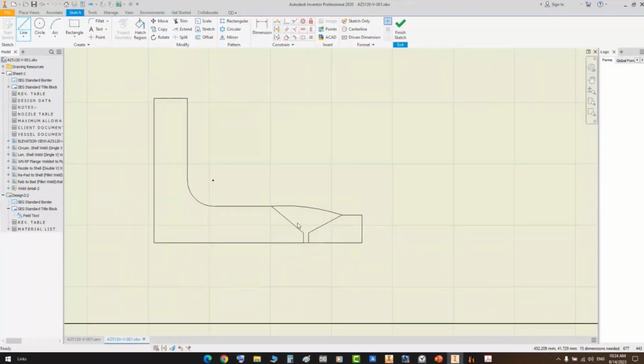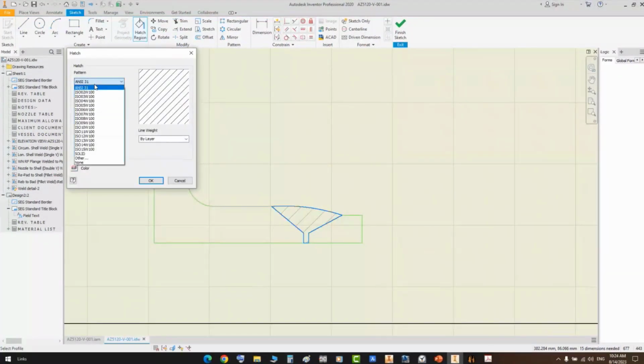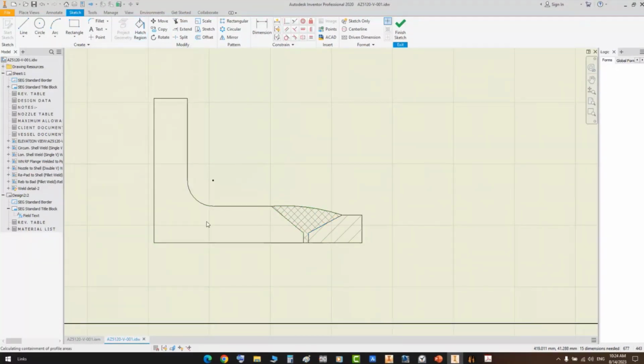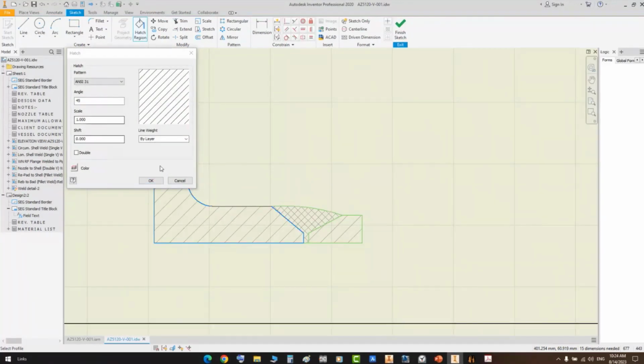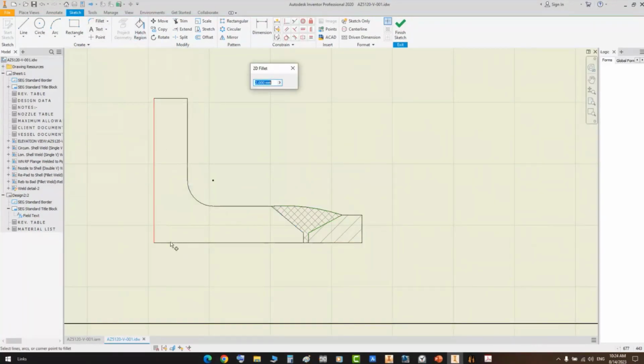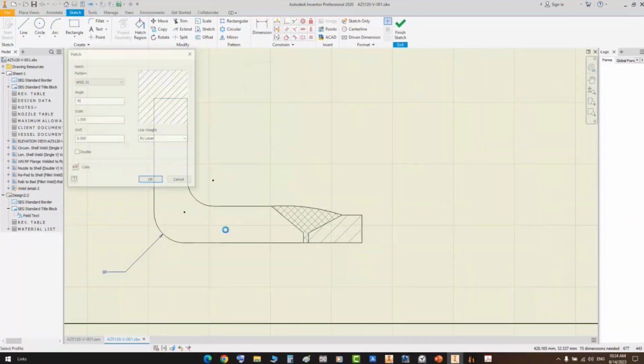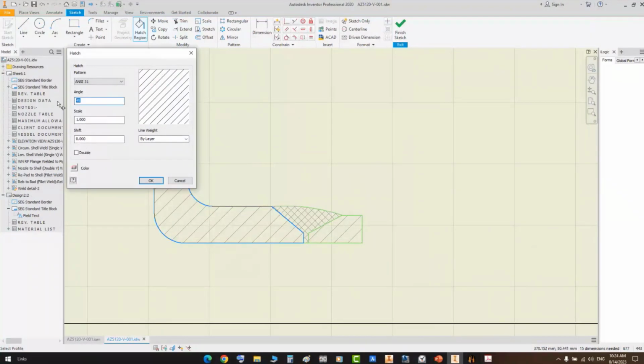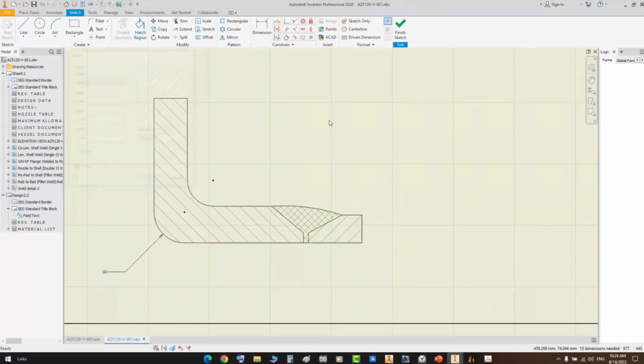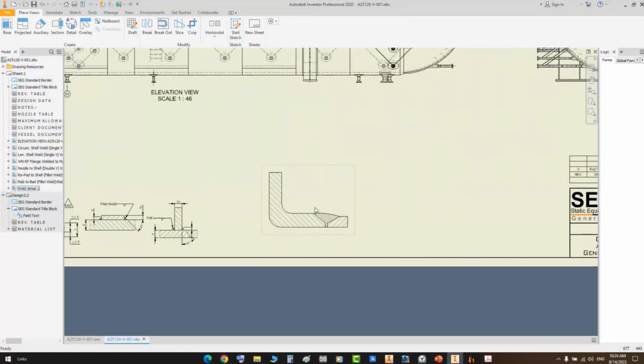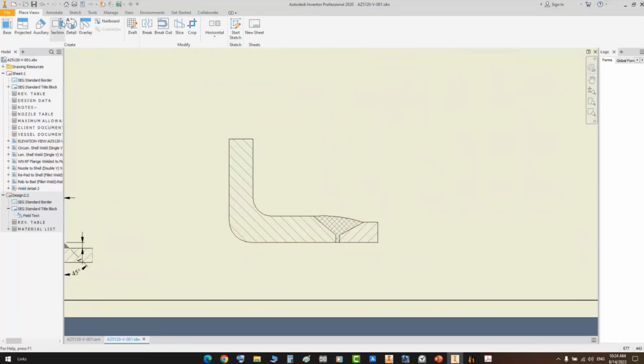After adding your dimensions, you can generate a weld detail like that. We add hatching like this, other hatching on that side. Let's make a fillet first. Here. And hatching. That, so you have here a new welding detail. For example, you can make something like that.